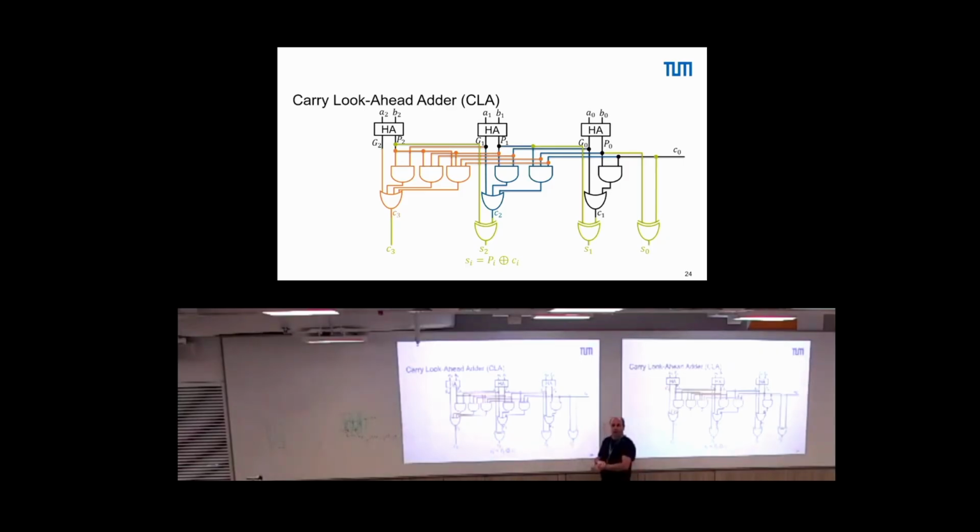What do you identify as benefits and drawbacks? So we have a shorter critical path. The size is increased. So the critical path here is in the worst case through one AND and one AND, one OR, one XOR, and here this half adder that generates the XOR. So if we draw it like this, it should be faster and it's larger because we need to replicate gates.